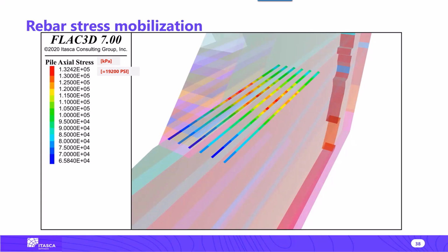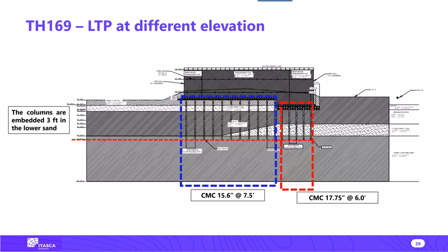So essentially what we're doing here is specializing two systems. One is the column, which is highly functional for vertical settlement and vertical displacement control. It is very poor in terms of horizontal control. So we are adding a component to the system that is highly specialized in taking horizontal displacement. And so the two support systems are collaborating together, one taking the vertical and the other taking the horizontal, even if they're not connected at all. Okay, this is the final project.